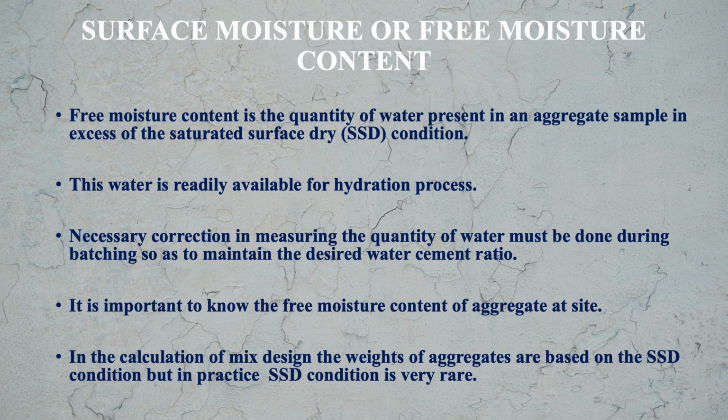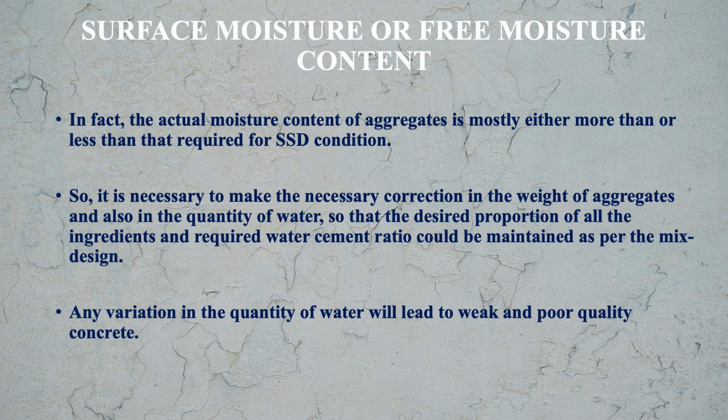In the calculation of the mix design, the weight of aggregates are based on the SSD condition, but in practice SSD condition is very rare. In fact, the actual moisture content of aggregates is mostly either more than or less than the required for SSD condition.